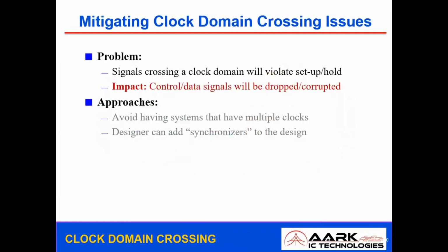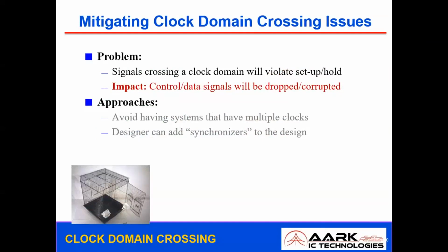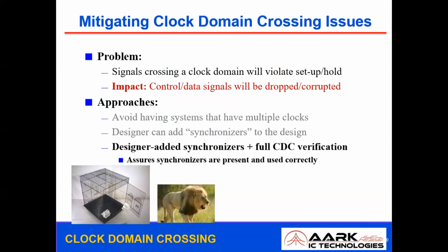The problem: signals crossing the clock domain will definitely violate setup and hold. As we discussed, the big impact is on the control and data signals. They will either be dropped completely or corrupted. We have seen the approaches also: designers should add a synchronizer plus full CDC verification.